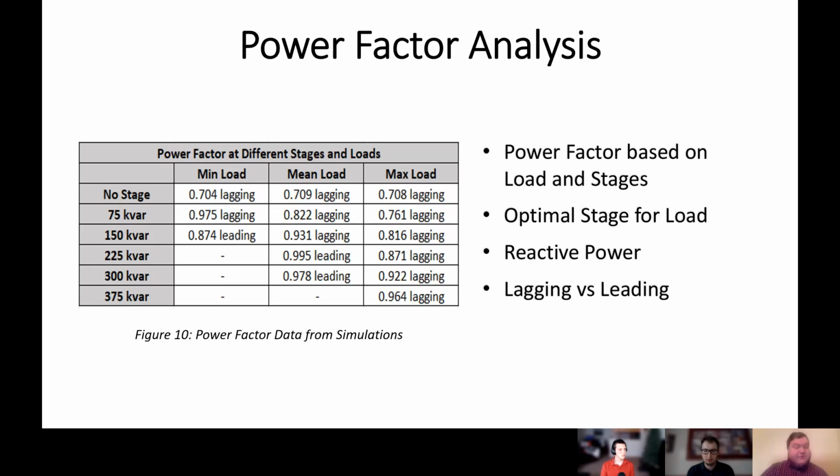Commercials don't want that. Their power factor is getting worse, and we've got reactive power being pushed back onto the grid. Lagging versus leading. Like I said, lagging is when the current is lagging behind the voltage, while current is leading versus the voltage in the other scenarios. A lot of times it's when there is more kVAR coming from the capacitance, reactive power coming from the capacitors, than there is from the load. That is when leading is occurring.